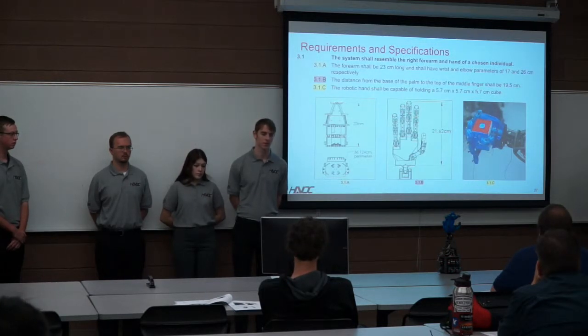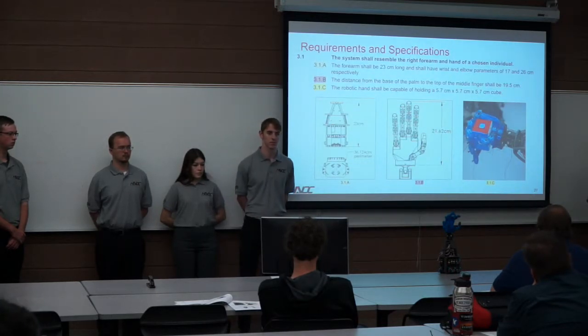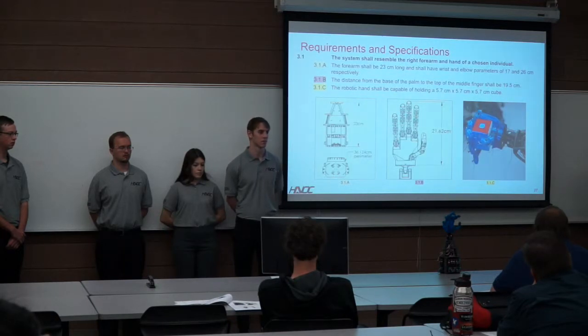We were able to maintain our length specification, but we were not able to maintain our perimeter due to a choice to make larger servos into our system to maintain our torque and rotational angles. As for our second specification of the hand size, we had to make the hand larger in order to ensure that we could reach all the positions within our task space.